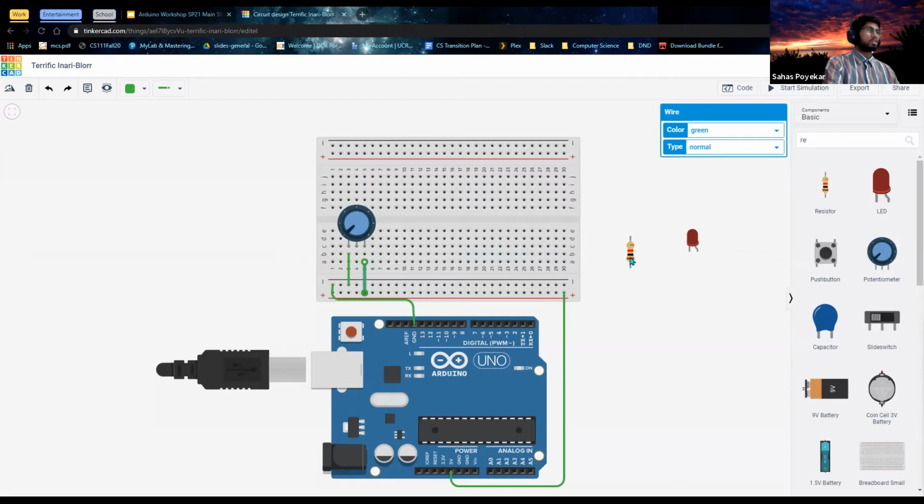I'll use a resistor to hook it up, and you would want to use the spin tool to spin it so that all of the bars on the resistor are on the right-hand side. I'll have it connected to the wiper, and I will start to hook it up to my LED. I'll have it in parallel with terminal 1 of my resistor with the cathode, and the anode will connect back to power. That's all we need in order to set up our potentiometer LED demo.